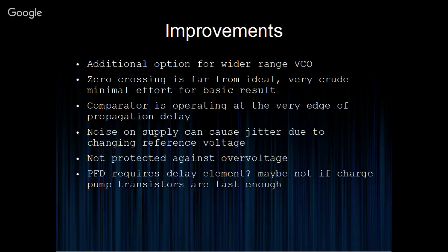The other thing to note is when you're using a current sink and a current source, at the time where they're both switched on, and provided the current source and the current sink are matched, you actually have net flow of 0 into the capacitor. So it doesn't matter. There's a lot of discussion about inhibit logic and trying to make sure they don't short out. Well, they're not going to short out because they're current sources. They're going to limit the amount of current that can flow through them. So there's no risk of short.